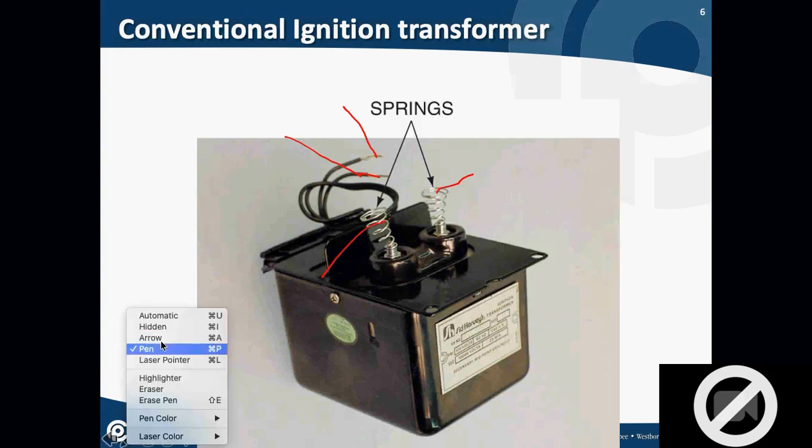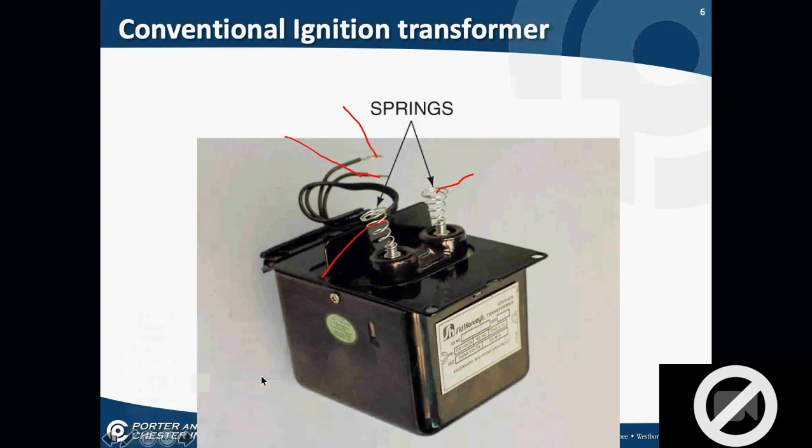Then I'm going to take a reading from here to here. What should I get? You should get 0? No. If I take a reading from there to there and get 0, I have a short across it. You should still get some number, right? No. OL. I should get OL. Remember, in a transformer, is there any electrical connection between the primary and the secondary side? No. So I should always get OL, ohming across the primary and secondary side.